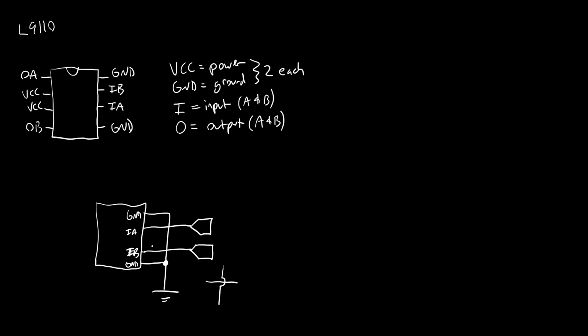But I have seen students get confused and think, okay, this must mean we're connecting all of our input signals to ground, which would make your microcontroller pins useless here because everything would just be tied to ground. So don't do that. These wires are not connected here. This datasheet is using this convention where things are only connected if you have a dot.